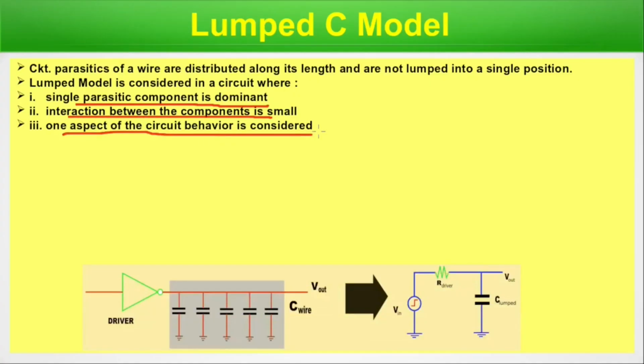This is the driver. This is V out, and that happens on the higher, more matured node. Capacitive action is more predominant compared to the resistive parasitic. So there we can approximate that there is no resistance, only capacitive actions, which are modeled by some capacitance. So this is the driver and this is the V out. That scenario is modeled like this, this is the signal. Then when it's on, we consider it as a resistor, and altogether all capacitances are lumped, their values are lumped into one, and that is the V out.